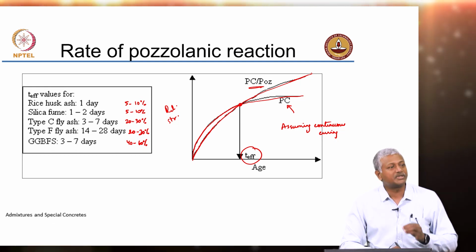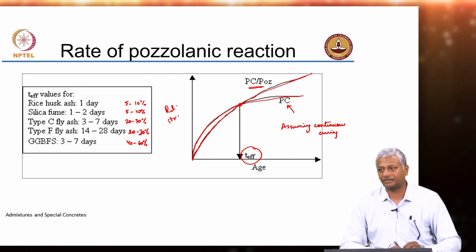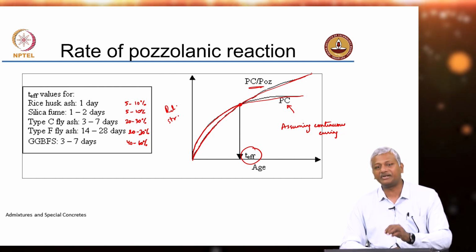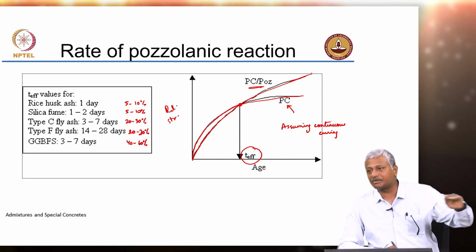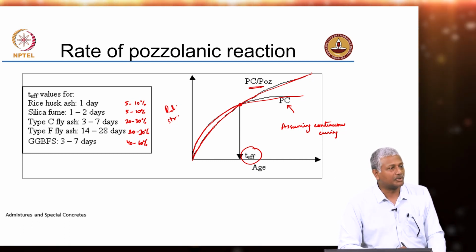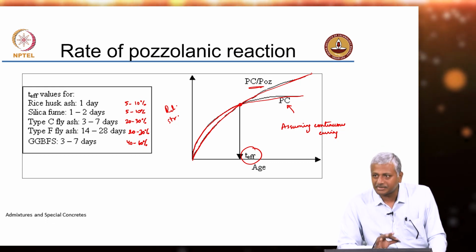So, one has to design the concrete to get the strength. It is not the cement strength that will dictate the concrete strength, unless of course you are working at the same level of cement content and water binder ratio. This is a concept which not many people understand.